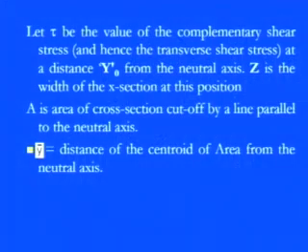So for that, there are complementary shear stresses just to balance the shear stresses acting. The complementary shear stresses are always there on the longitudinal planes, which are parallel to the neutral axis. And if I say that tau is the value of the complementary shear stress, corresponding to the transverse shear stress at a distance of y0 from the neutral axis z, then there is one more component which has to be defined,